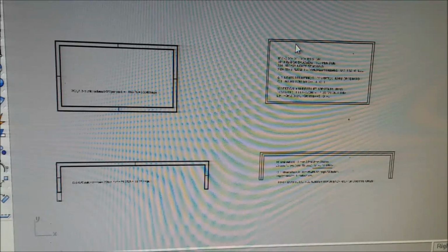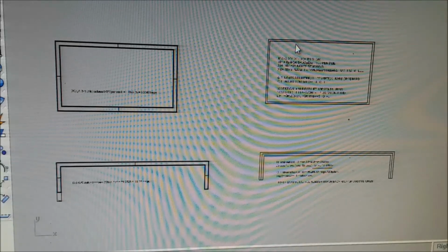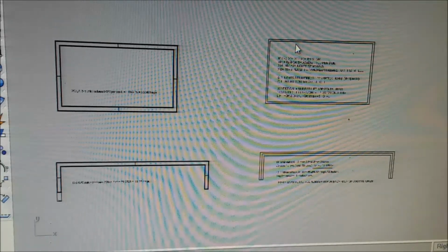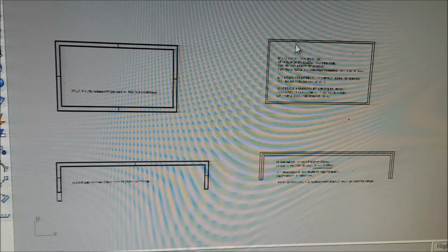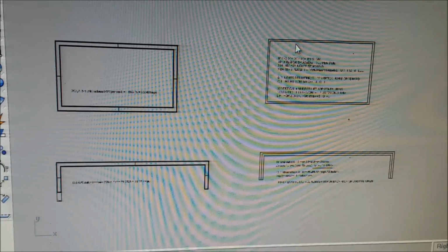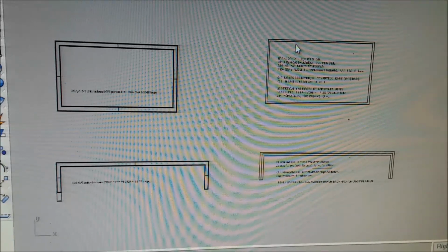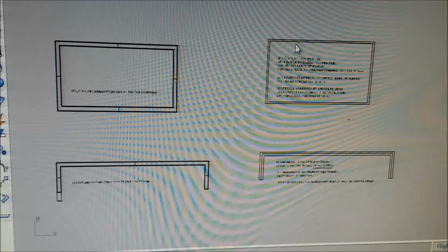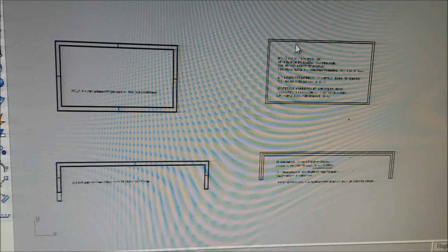And this will tell you if you have enough rock, sand, and cement on hand before you get in the middle of pouring something. Floors are done like walls. You know, the rebar is easier to calculate, but the cement, sand, and gravel is a simple volume. How thick's your floor and what's the area, and that gives you the volume. And divide it by 1728, and that gets cubic feet. Divide it by 5, that's the bags. It's fairly simple. And any kind of house has that.